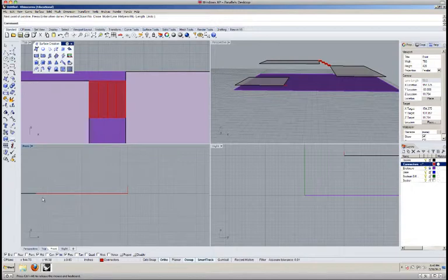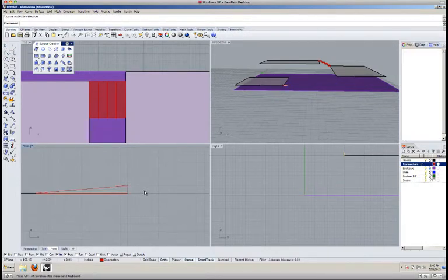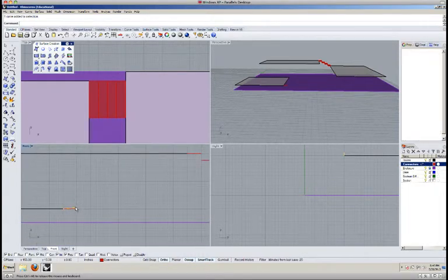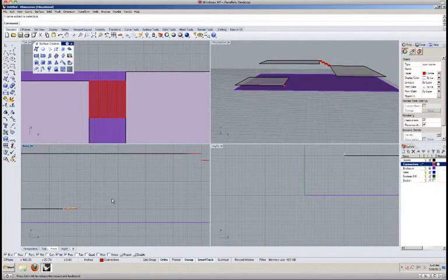So I can use that as my template, and then I can draw a diagonal line from one corner point, so from this end point to this end point. And the object snaps will allow me to override the ortho settings. So if I click to an endpoint, it won't make me keep it orthogonal. So from here, you don't want to take this and stretch it, or turn on the control points and drag one, because you're going to change the slope of the ramp.